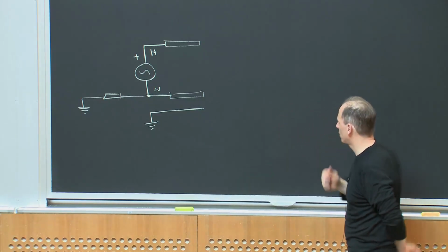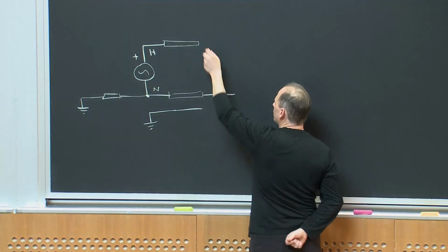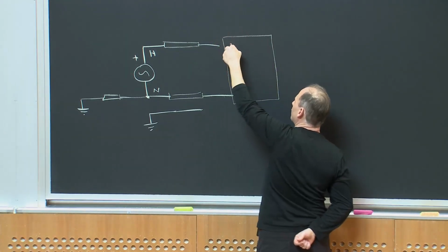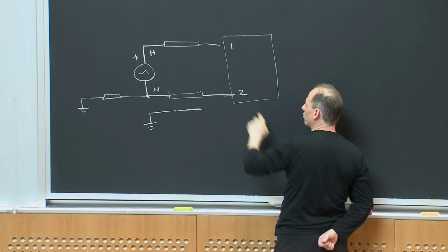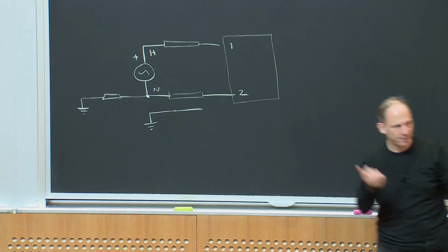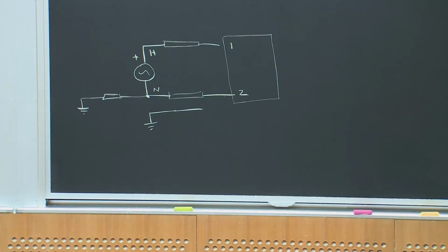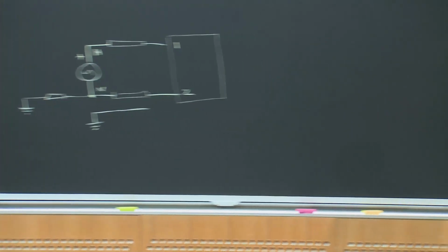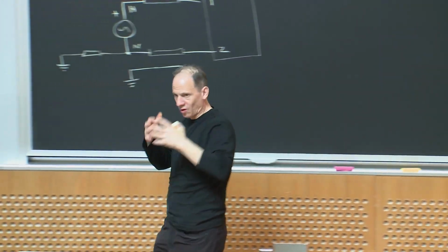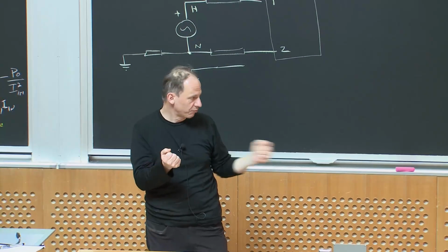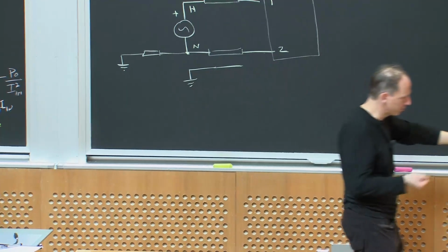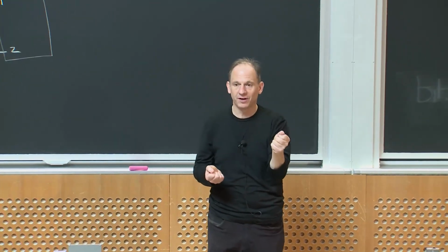So what happens again? Okay, this is going to plug into whatever my device is, and I'll have terminal 1, terminal 2, for hot and neutral. And then I may have some parasitic path. Why might I have a parasitic path? One reason is in a lot of equipment, we tend to ground the case of the equipment. So if it has a 3-terminal plug, you plug it into the wall, that ground connection coming out of that 3rd terminal is going to the case of the device.